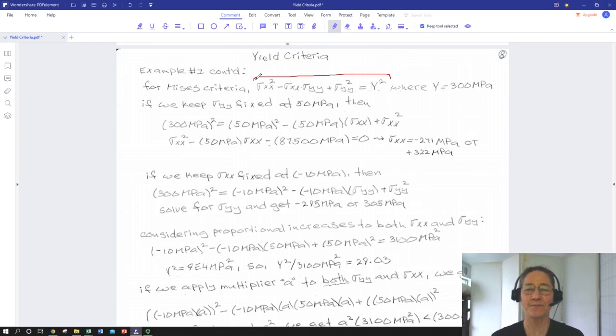What we're doing is saying, hey, wait a minute, I know something about this material. I know that it yielded when a uniaxial test was done to a value where my uniaxial stress was 300 megapascals. So I'm going back and doing what we did at the end of our Von Mises discussion, saying I'm going to insert a known yield criteria that is based on a uniaxial loading, which I can relate to a Y from the Tresca criteria, which says uniaxial stress, in this case applied uniaxial stress of 300 megapascals yielded.